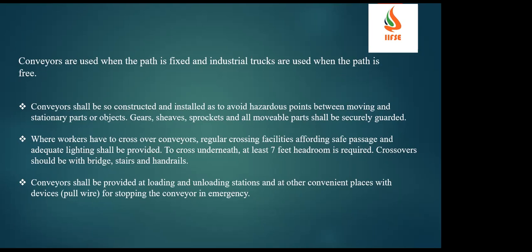Yeah, most of the safety factors will be maximum, they will give 5 or 7. In my experience, I have seen these 2 safety factors. Most of these lifting web slings and all, nylon ropes or nylon belts or these labels, they will come with a safety factor of 5, or some belts they will give a safety factor of 7.